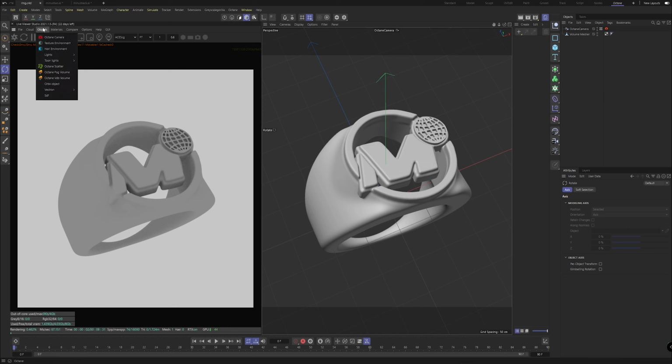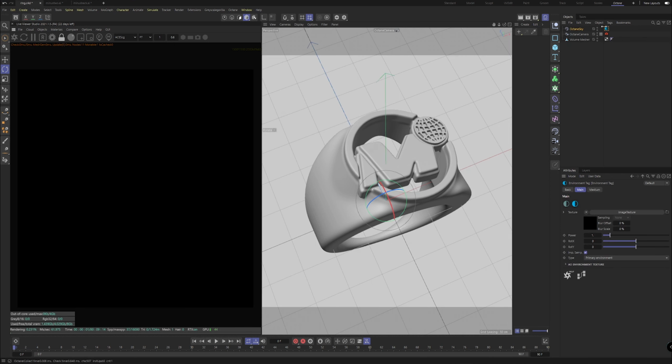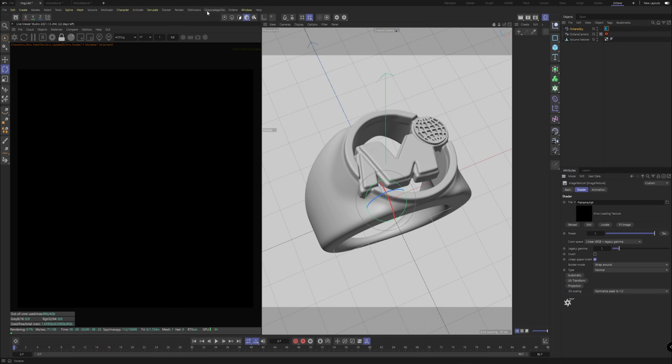And we can grab ourselves a HDRI environment. So I'm thinking the HDRI doesn't matter too much because it's going to be the environment that you're looking at, right? So for this, like the style of this brand and stuff, I feel like almost like a graffiti type HDRI environment would be quite cool. I believe I have access to that. Grayscale Gorilla might be able to pull through. So we just wait for our Octane Sky to load. We can head to Grayscale Gorilla up here, plus library.